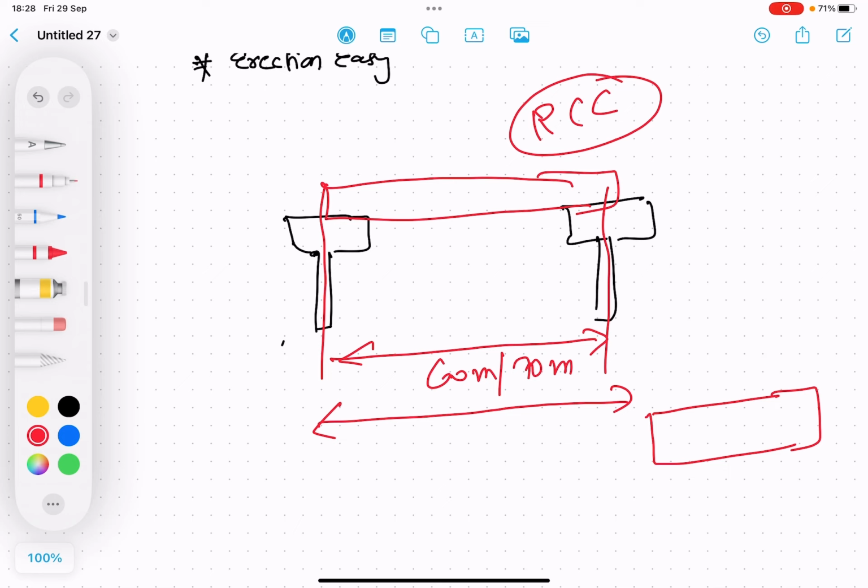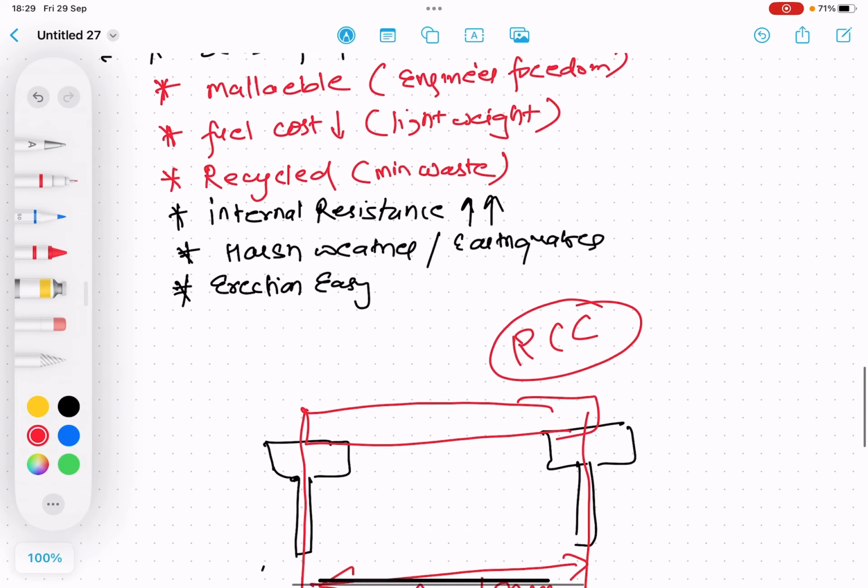We first do the steel structure erection, and upon it, I sections, basically steel girders, are erected, and over that the casting is done. Okay, and thus deck slab casting is done. In this way the material cost is also saved, and these steel structures have more strength. The same steel structure has more strength than RCC. So this is one of the examples, the advantage.